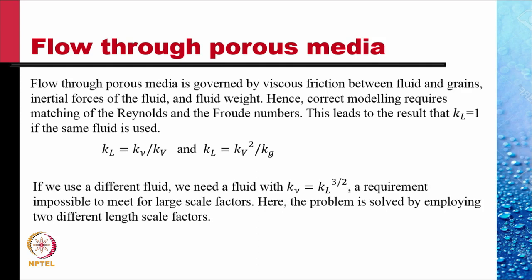If we use a different fluid, we need a fluid with a scale factor of kinematic viscosity as KL to the power 3/2, a requirement impossible to meet for large scale factors. Hence, the problem is solved by employing two different length scale factors.